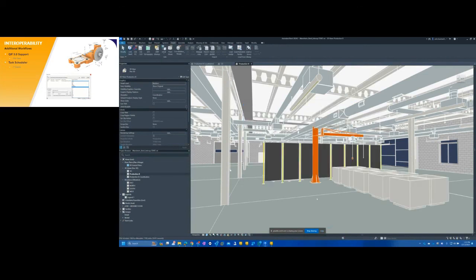And you can see that it's brought that Revit model into Inventor. And again, it knows to place it in the correct location, because when we did the initial creation of these models, we made sure that they're using the same coordinate system. So that's how it knows. And if you look here, just where my cursor is, you can see that there's that interference that's happening there.